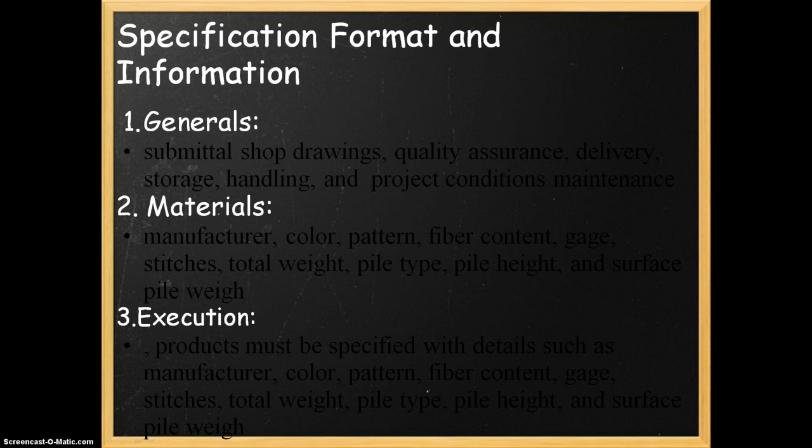And then in the last part, execution, you have to specify verifications for the conditions and written requirements for the preparation before you put in the flooring and after. Also the installation method, the protection, and the schedule for when everything will be installed.